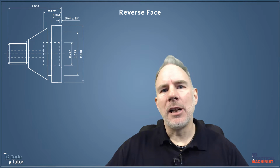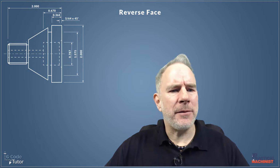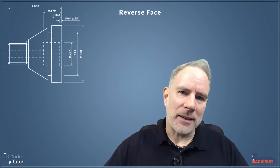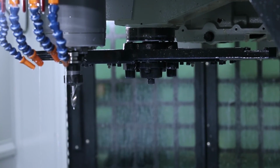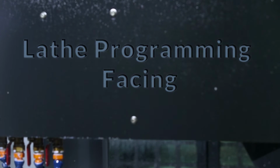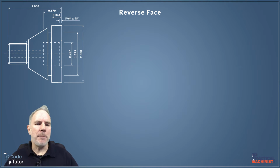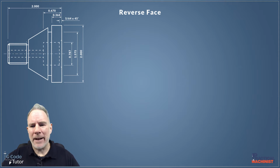We're programming a part using G-Code on a CNC lathe. So this week we're going to reverse face off the back end of this part. What we've done so far is we've machined this part complete. We have done all the external and internal parts from the other side. Now we've parted it off, we're just going to face off this back face to get rid of that bad finish from the parting off tool. So let's jump straight into it.